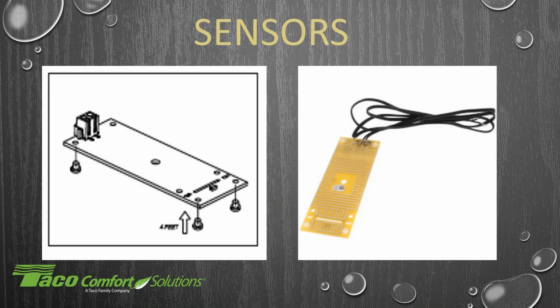All right, so here we can see the sensor itself. What the sensor also comes with are these little plastic feet that snap into the bottom if they're not already installed, and that is designed to sit on the water heater pan. As it sits on the water heater pan, we make sure we don't have any accidental activations from the metal pan making contact, or a damp concrete floor. We have some basements out there with high humidity, and the concrete floor might be a little cold, and have some accidental activations.